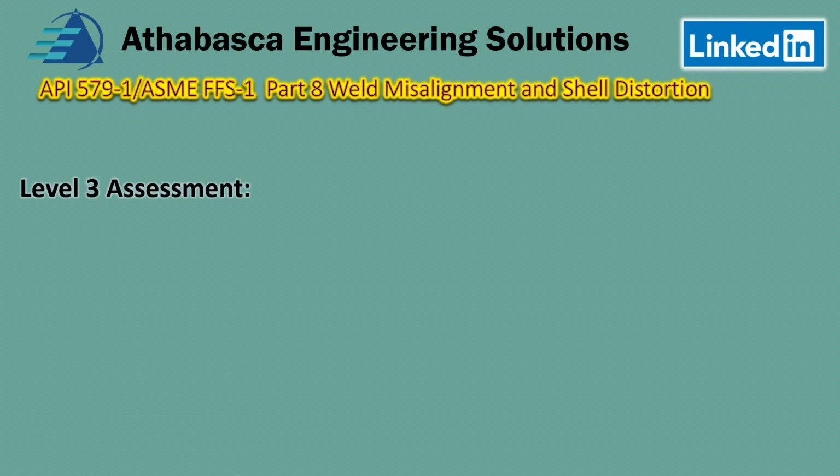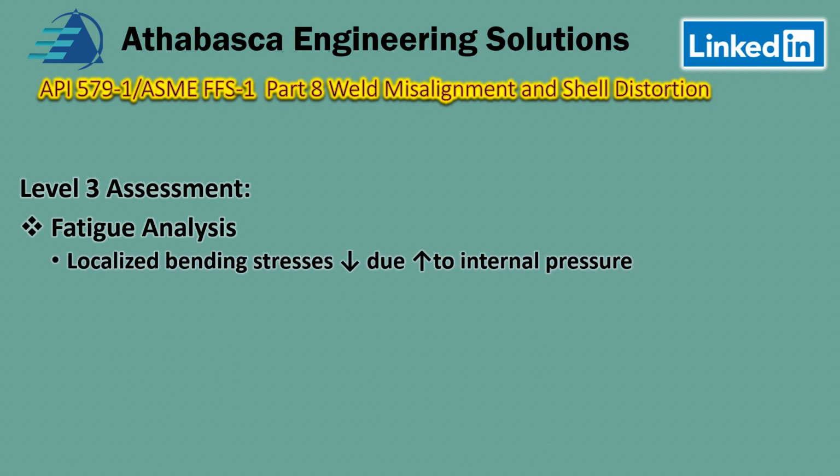Here are thoughts that API presents when doing a Level 3 assessment. It's a very condensed document, but here are some thoughts on fatigue analysis. Be aware that localized stresses can be reduced if you have an increase in pressure. It's like when we used to analyze underground piping systems.